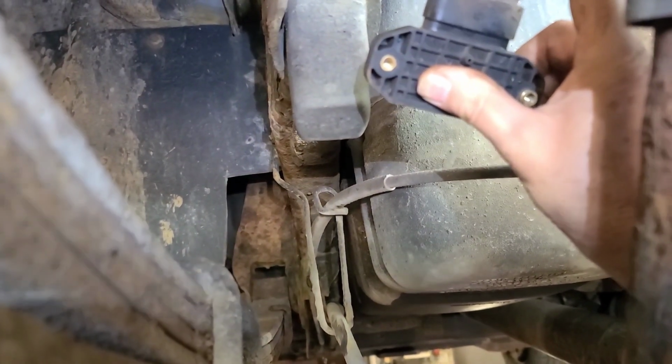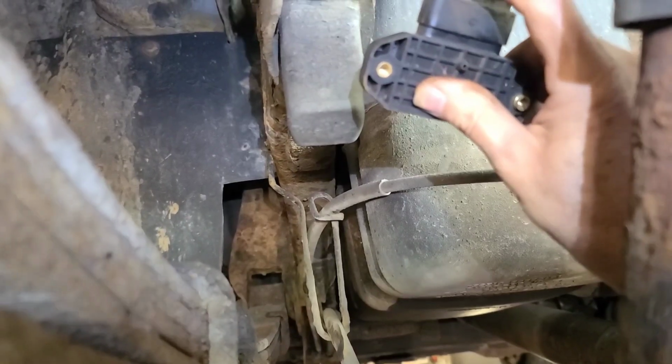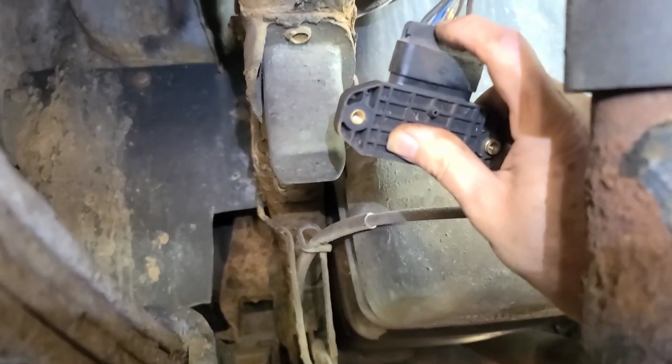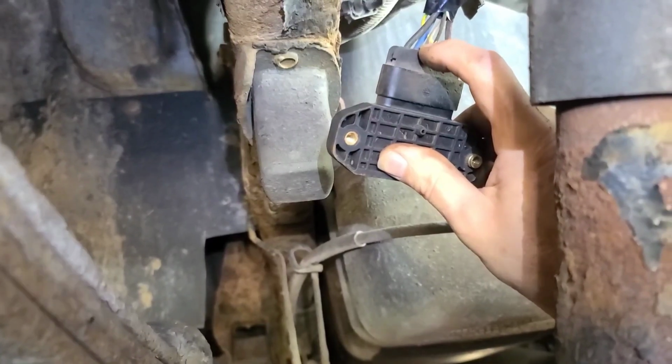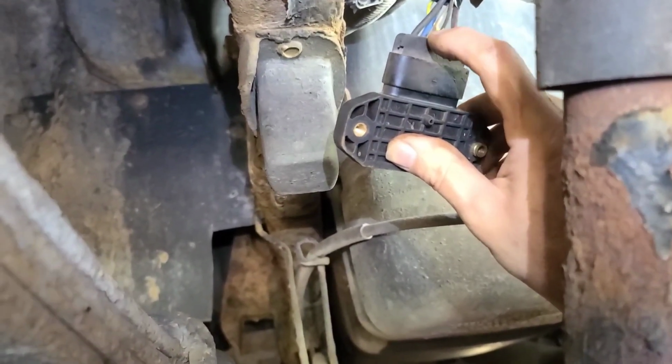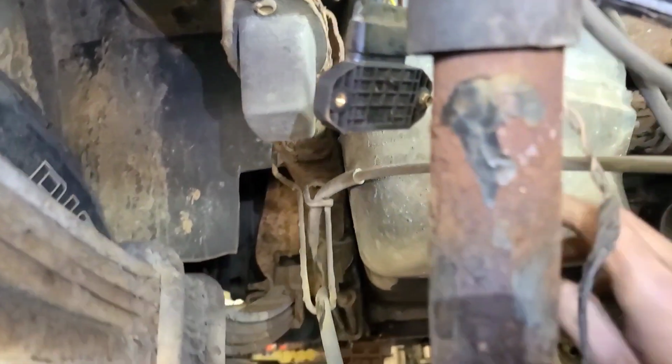So these 2 big wires, and then the blue wire goes out to the trailer brake plug-in. So we'll check continuity of that wire. We'll load test that. We'll send power from there to there and see if we have, it'll light a headlight at least.